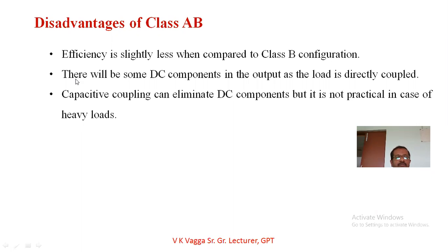And there will be some DC component in the output if the load is directly coupled. On using direct coupling, some amount of DC component may be available at the output. And capacitive coupling can eliminate the DC component, but it is not practical in case of heavy loads.